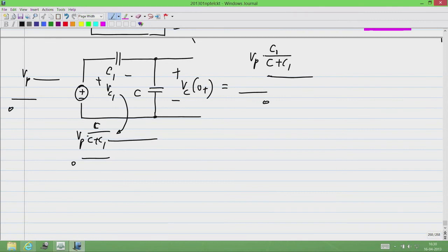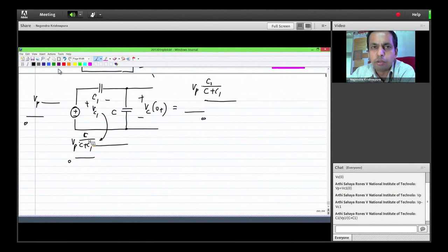So, when you have a loop of voltage source and capacitors and you apply a step, the voltages of all capacitors in the loop will change abruptly. They have to. So, that I explained, and now you can also calculate how much they change by, and all you need to do is to write down KCL in terms of charges instead of currents. That is all. Any questions about this?